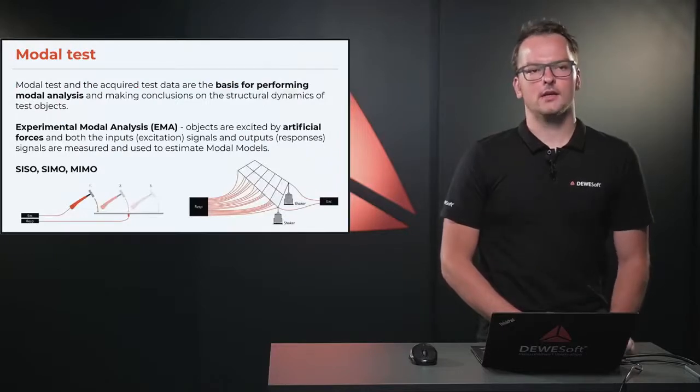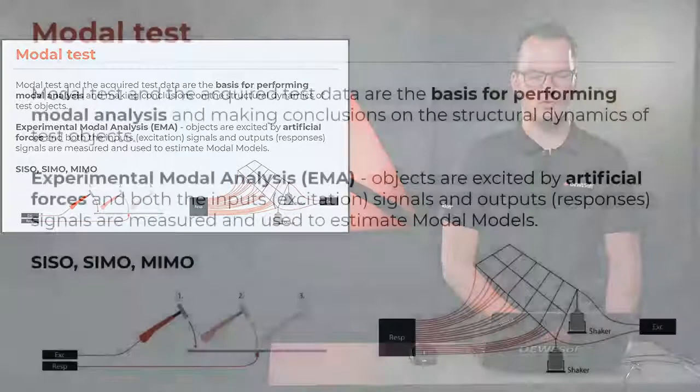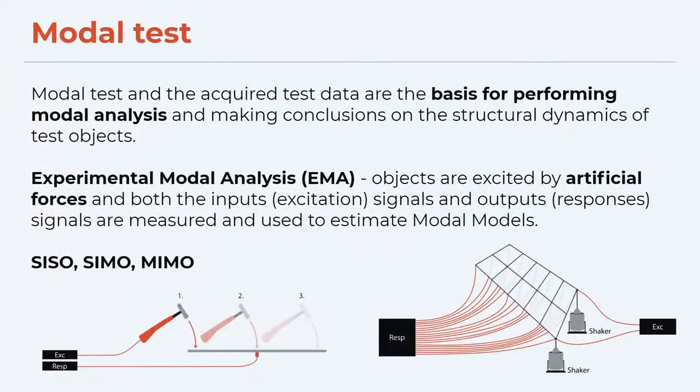So let's briefly take a look at the modal test. The modal test is the base for performing modal analysis and to even make some conclusions on the structural dynamics of test object. In Dewesoft, we support experimental modal analysis where objects are excited by artificial forces, and we measure both excitation signals and response signals. And we support a lot of different configurations, from single input, single output, to single input, multiple output, and also multiple input, multiple output configurations.